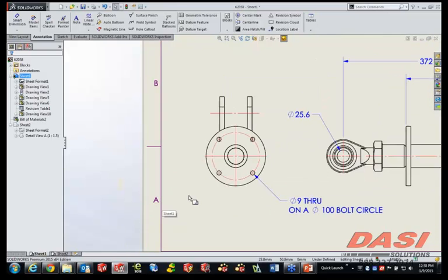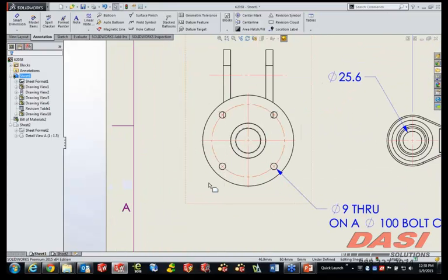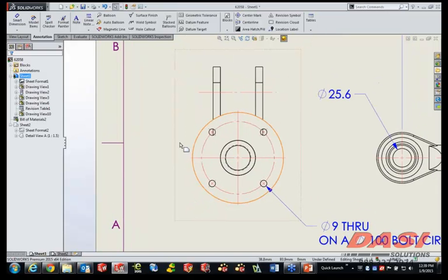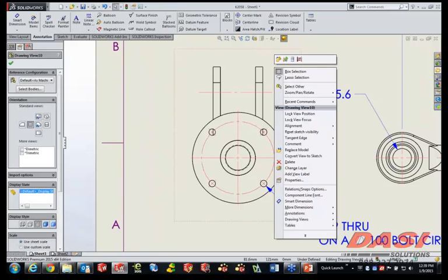Down here in the lower right-hand corner, I want to look at some center marks. Center marks are one of those things where, based on changes, these can go broken. And it's just a fact of how parametric systems work. I'm going to open up this assembly in this view. I'm going to right-click inside the view, and instead of choosing the original open part file, we have another one to the right of it that actually says Open Part in Position.